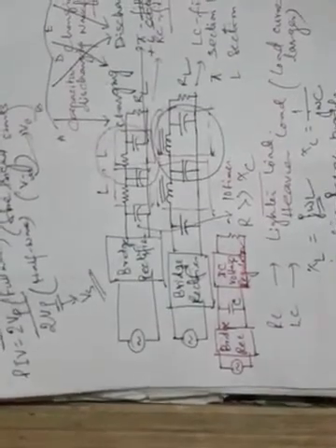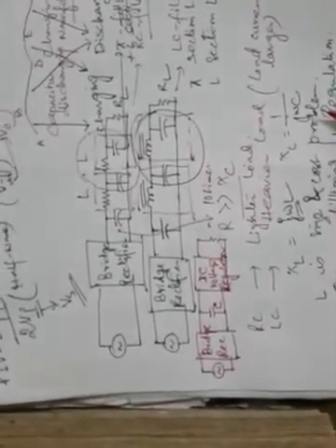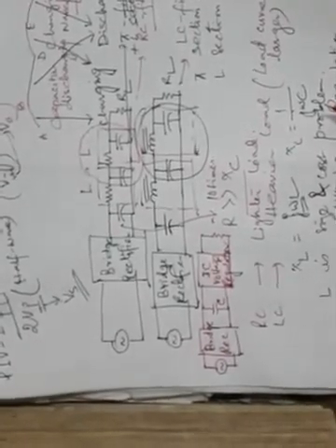So this IC voltage regulator is an integrated circuit made up of diodes, transistors, resistors and other components. That means in some cases active devices also, not only passive devices. This device not only reduces the ripple, that means it helps us with the filtering purpose, but also holds the output voltage constant at a particular level, thereby the regulation is achieved at the output of the rectifier along with the filtering scheme.